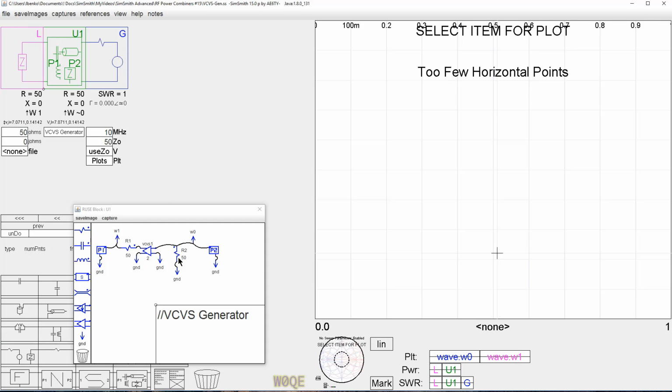We have a 50 ohm load here, so we get the correct voltage right here. We have a generator that takes this voltage here, does not draw any current. It's high, infinite input impedance. It's a mathematical symbol only. It's got a gain of 2, a new 50 ohm load resistor in series with the generator, and then an output. So if we look at this circuit, what we see is,